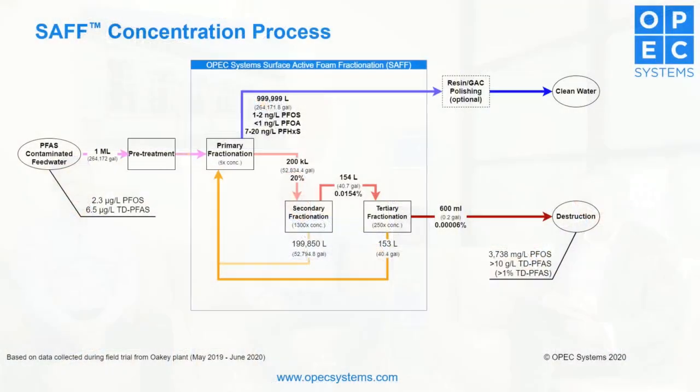Yeah, so concentration is really where the art happens. That's the hard bit, if you like. What we're trying to do is take the primary fractionate that we get off that first step, and then we've got to dewater it. We want to dewater it a lot because we're dealing with millions of litres, and even if you're only getting 1 or 2%, it's way too much to practically deal with. So we have to get really good concentration factors for this to be effective for our clients.